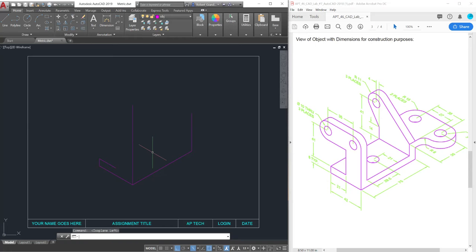most pencil and paper setups. I'm going to start my ellipse, and you'll notice there are 3 different ellipse functions here. I'm going to pick the center one, and then you'll notice it's asking me for the center of the ellipse, and I'm going to pick this point here, and now it's asking me for the end point of the ellipse. So I would have to know what the distances are in this case if I didn't know what the actual major and minor axes were on these ellipses. So I'm going to cancel out of that ellipse command and call your attention to this one.